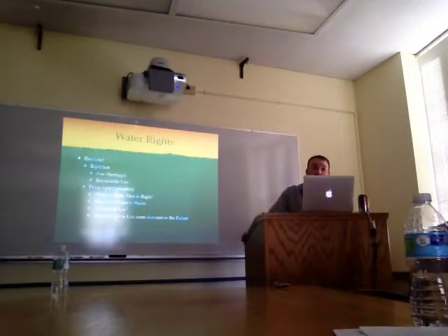So we touched on this a little bit a couple of classes ago with the two systems, one riparian, which basically is reasonable use of it, a lot of more eastern states where there's no water shortages, in comparison to the western states, which follows the prior appropriation approach. And those, again, it's that first in time, first in right, and you have to actually claim the water that's government owned for beneficial use, and then once you've actually established that beneficial use, you attain vested rights into that amount.